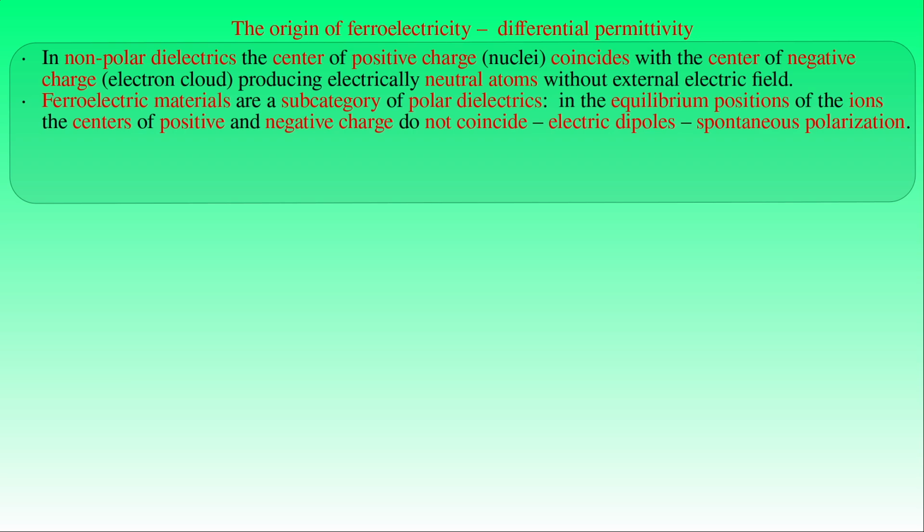Ferroelectric materials are a specific subcategory of polar dielectrics, that is, they have a crystal structure in which the equilibrium positions of the ions are such that the centers of positive and negative charge do not coincide. As a result, ions behave like electric dipoles, producing spontaneous polarization even if no external electric field is applied to the material. In thermal equilibrium, the molecular orientations in common polar dielectrics are random, so the average polarization in the matter is 0. Under the influence of an external electric field, the electric dipole moments of the molecules tend to align in the direction of the field.